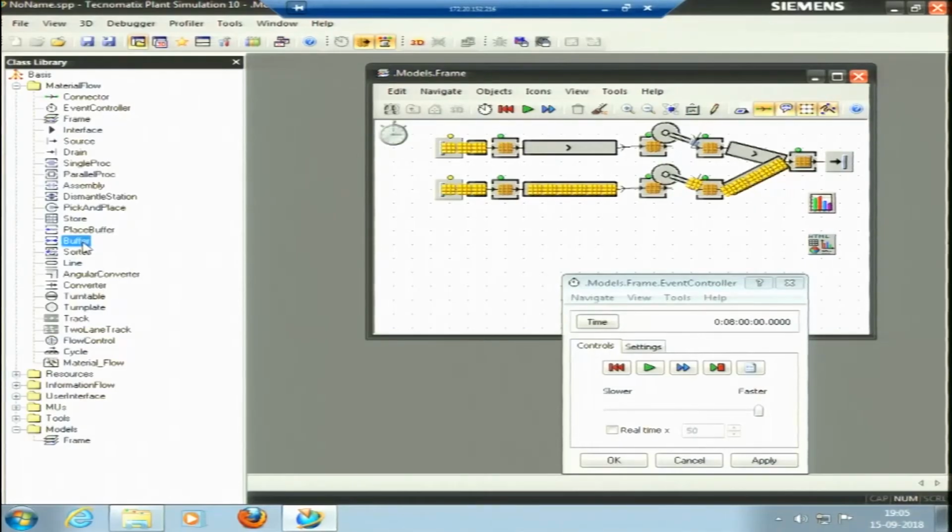The big buffer is placed between 2 plant components for certain purposes. It temporarily holds parts when the following components fail, okay, when the successor is not able to receive the component. The second, important function it does is it passes the part on when the preceding components stop working. The dimensions of a buffer with large enough capacity for covering all failures lead to complete decoupling of the plant and the other attributes as well.